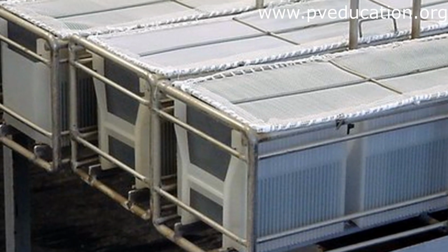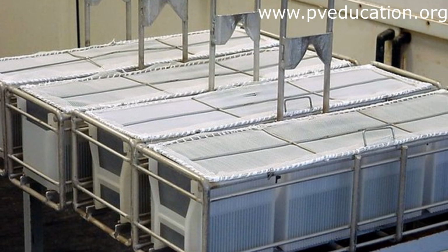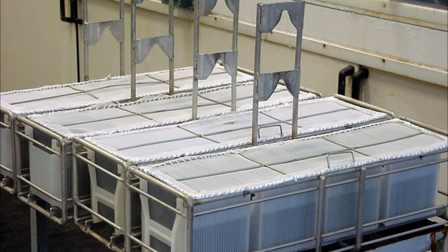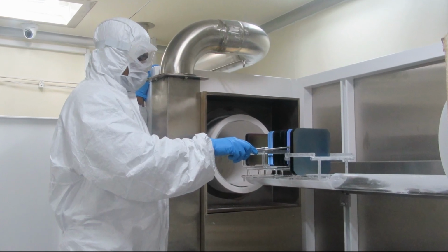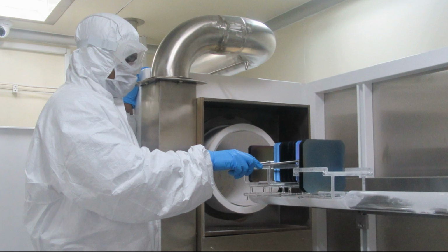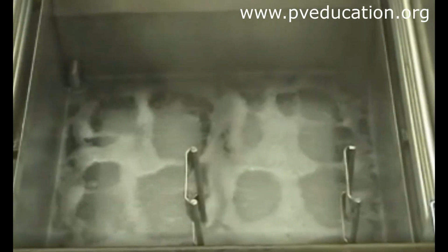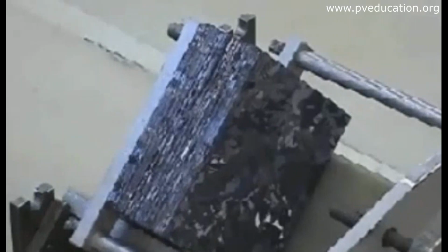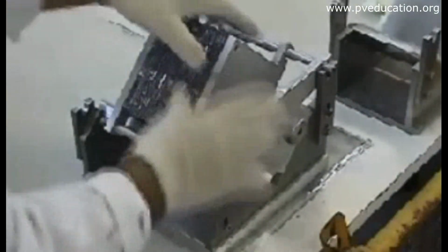Next, the textured silicon wafers are taken in a batch and put inside a diffusion chamber for inserting an n-type layer on the top surface of the p-type substrate. This process is done at a very high temperature, in presence of gases like POCl3, nitrogen and oxygen. An unwanted phosphosilicate glass (PSG) layer is formed during this process, which is chemically removed. Next, the front and rear surfaces are electrically isolated by removing the surface layers by either plasma or chemical etching.